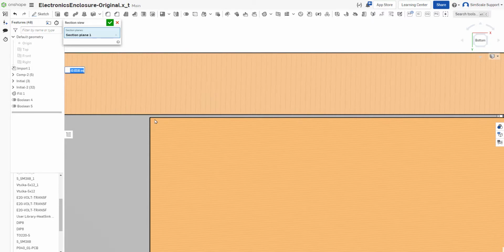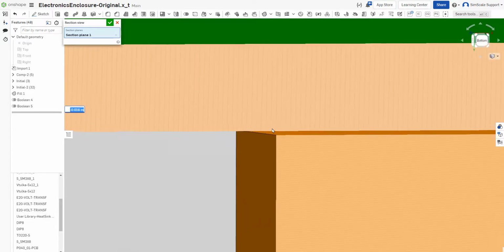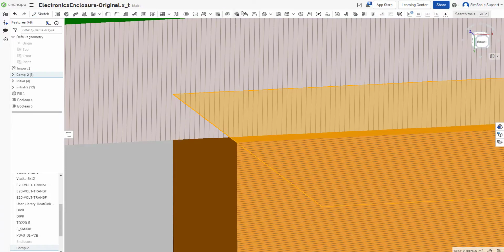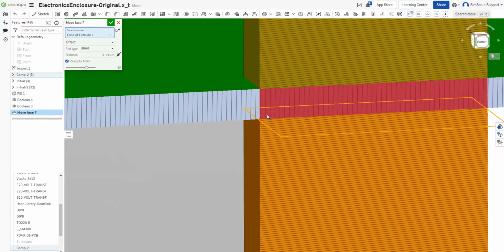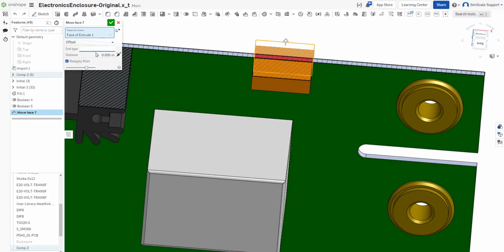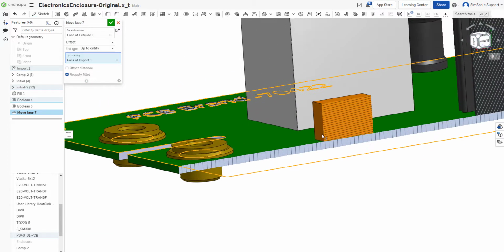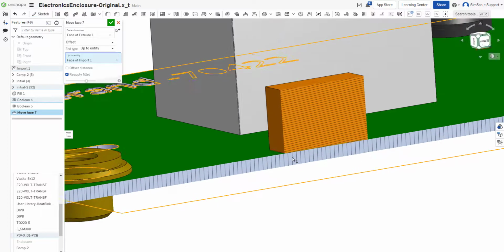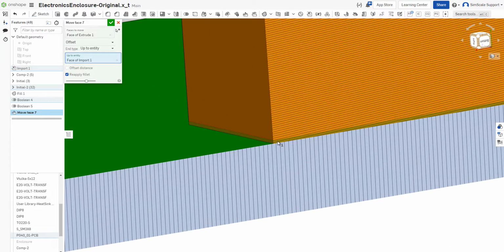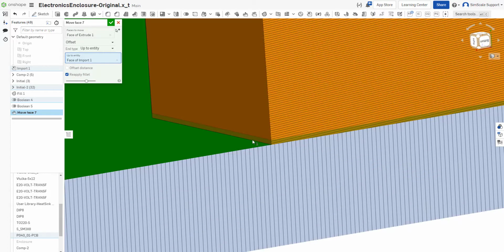This will prevent the automatic contact detection and hence there won't be any thermal contact between the PCB and the component. To fix this, we need to make sure we extrude the face of the component until the top face of the PCB. Once again, these operations might be slightly different in other CAD tools, but would be easily replicable. By extruding the component until the PCB, we are making sure there is proper contact between the components.